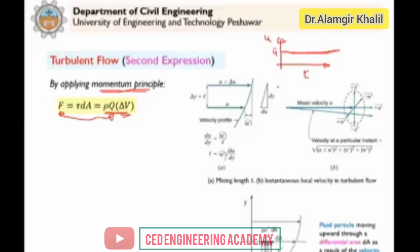This is the time average. Then we have these fluctuations, which are due to the turbulence. They go up and down, and this happens in all three directions. Clear? At any point here, the fluctuation can be represented by u dash.